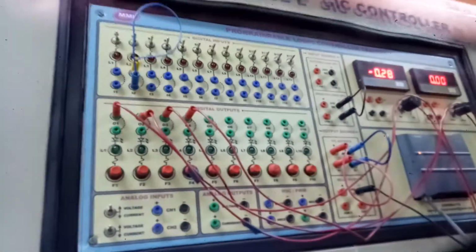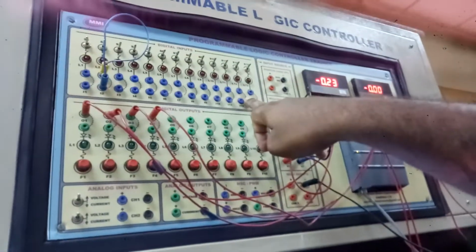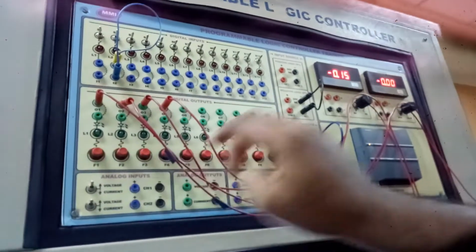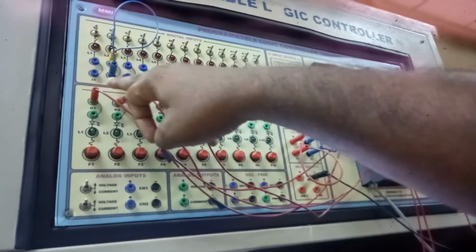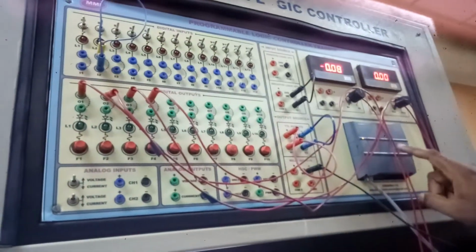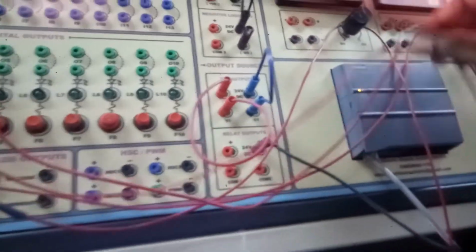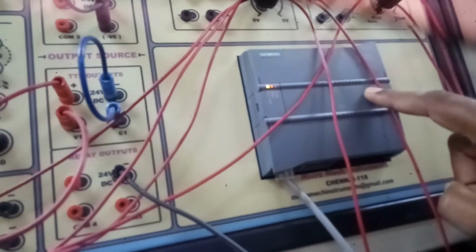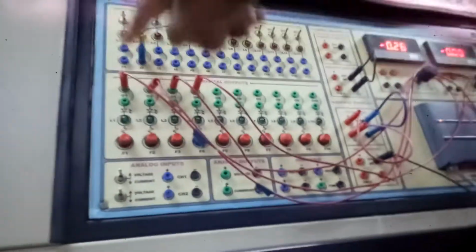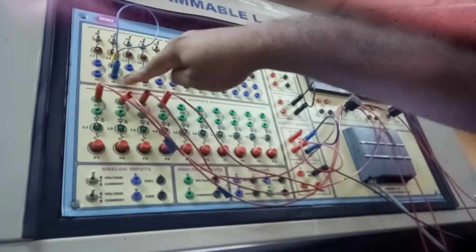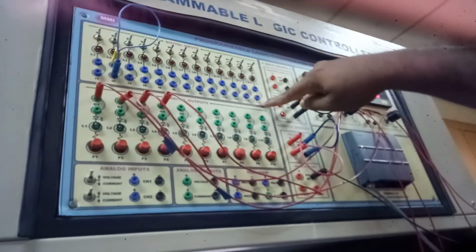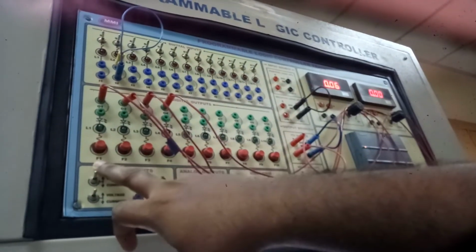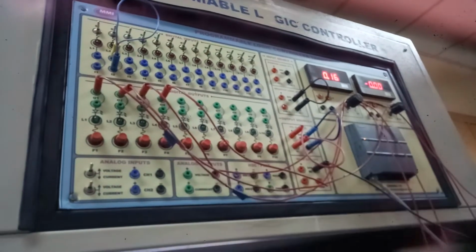This is a PLC kit. In that kit they have around 13 inputs, and we are able to get 10 outputs. The names they gave are I1, I2. In that PLC kit they mentioned 0.0, 0.1, 0.2 like that, so we go for that same order. Here also we mention this is 0.0, 0.1, 0.2, 0.3 like such, for giving the inputs. In the case of output, this will be 0.0, 0.1, 0.2. So output is Q 0.0, input is I 0.0.